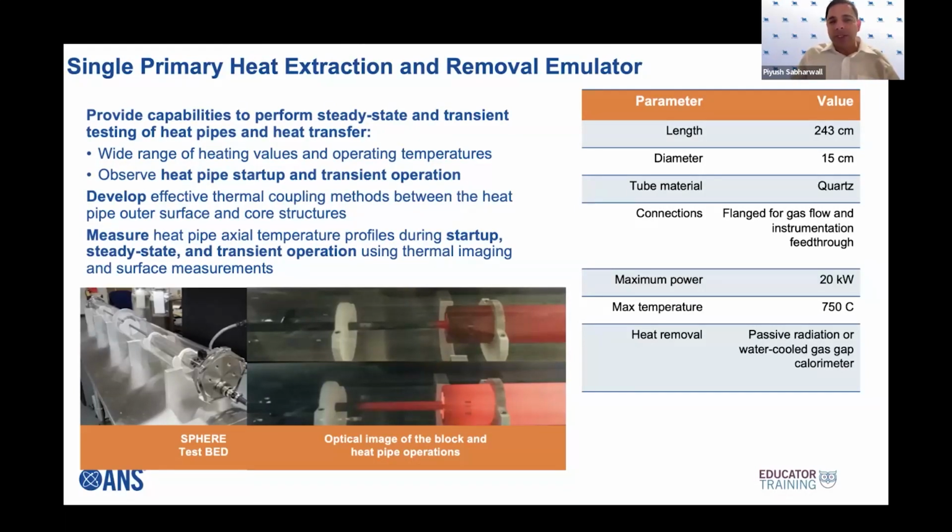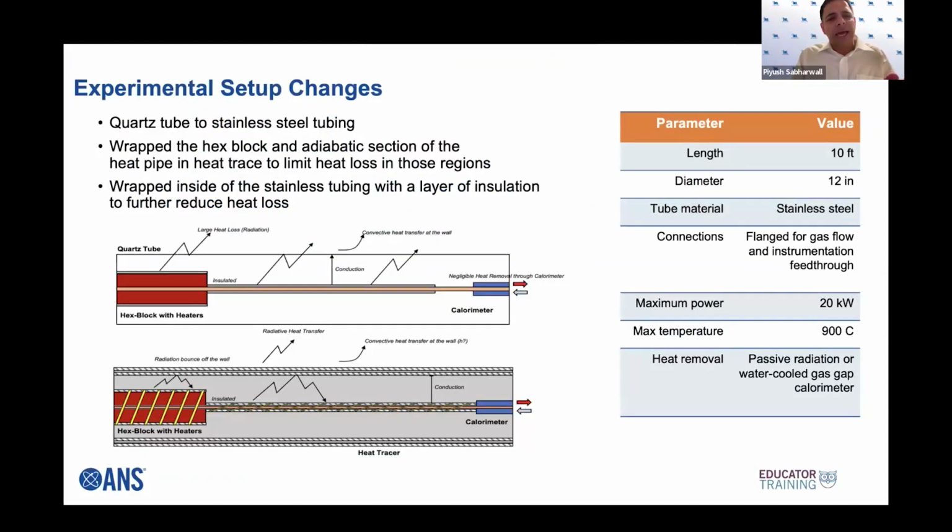Some of the codes out there still assume your alkali metal to be in a molten state, which is not the case because you got to provide heat to melt those things, right? Again, it's alkali metal, so it needs certain temperature to be molten. So we started, this is a 20 kilowatt setup. When we did an experiment, it worked. But as you do these experiments, you learn and leverage. So as you can see, we did this with the diameter 15 centimeter. But in a couple of cases, we saw that we were having some challenges. We were getting into some shortenings of thermocouples.